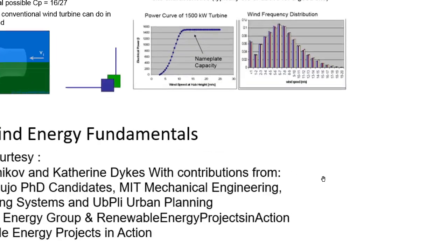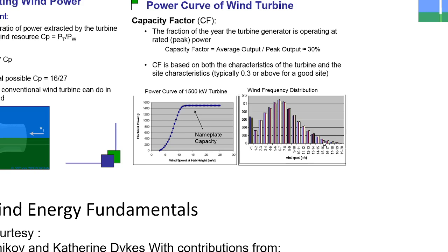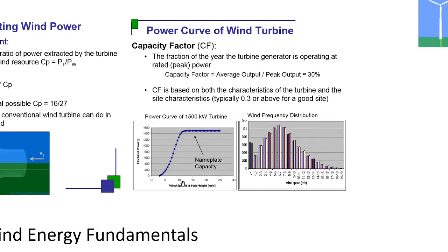It is not so difficult. So you have to have the number of hours of operation of the wind turbine. You should have the number of hours of operation from the probability of wind speed distribution at the site, assuming that the grid was available 100%.